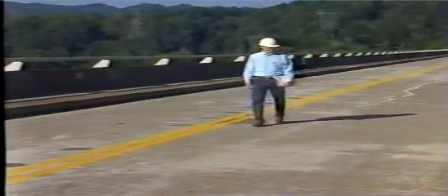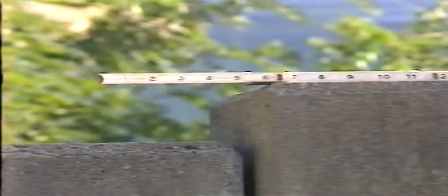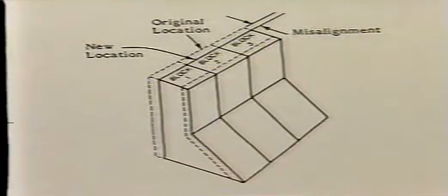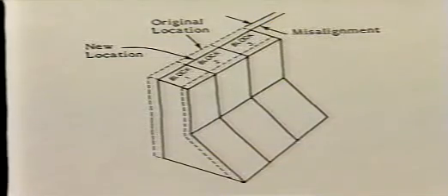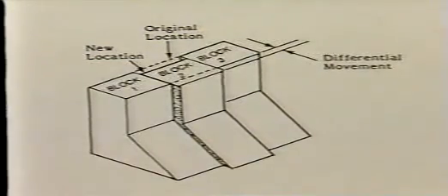At a concrete dam or concrete appurtenant structure, look for cracks, displacement, deterioration of the concrete, and leakage. Some cracks are serious, others are not. You should report any crack that has recently appeared, has enlarged in length or width, or exhibits displacement. Displacement can also occur at concrete joints. There are two types of displacement: misalignment, which occurs when the entire structure or feature moves, and differential movement, which occurs when one part of a structure moves in relation to an adjacent part.